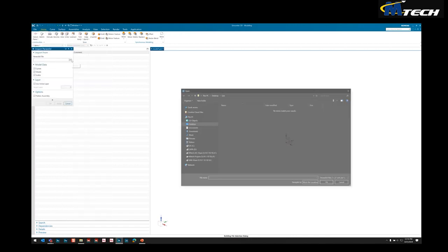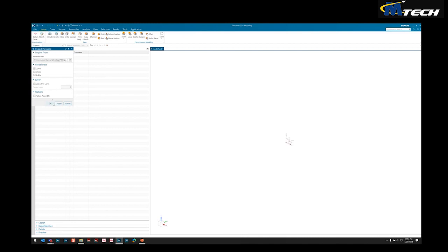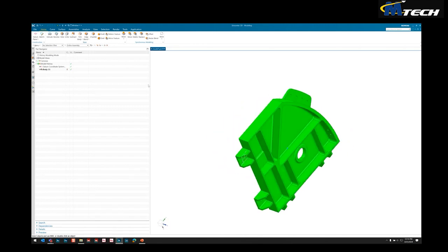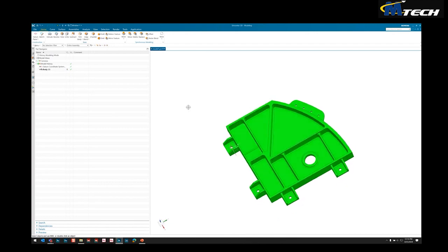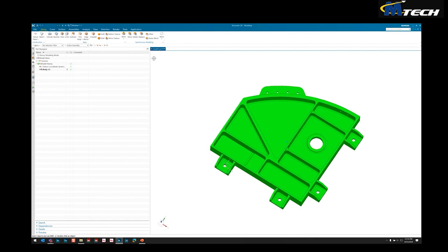So this parasolid file does not have history or feature-based modeling. So you'll see there's no items here. It's not parametric. It's just the common transferred file format. Think of a step file. So we can create parametric features, and we do this with synchronous modeling.